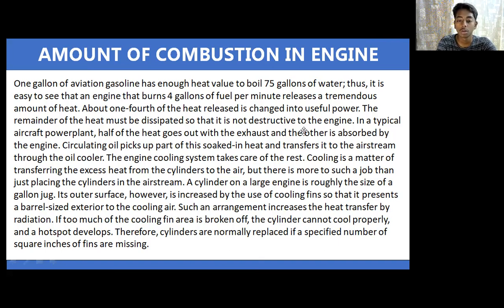If too much of the cooling fin area is broken off, the cylinder cannot cool properly and a hot spot develops. Hot spot means, as we have seen in the earlier slide, it turns into an orange reddish color at a particular part. Therefore, cylinders are normally replaced if a specified number of square inches of fins are missing. So this is how combustion heat is handled in an aircraft engine.